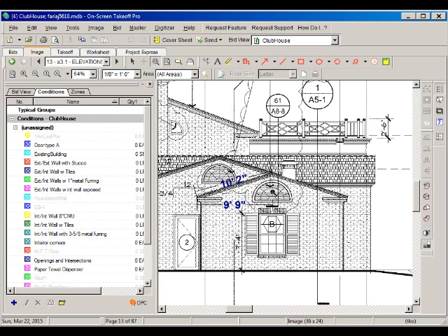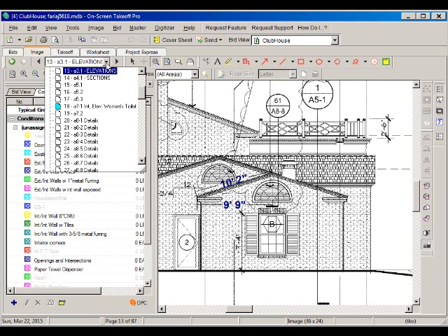Another possibility for this particular wall is to use a height that is the top of the beam plus 1/2 of the elevation for this roof. That's going to take into consideration half of a rectangle that covers this area, which then will result in the area that we want to estimate. So as you can see, there are different ways to do this. I am going to use one triangular area and one linear condition to estimate these sections.